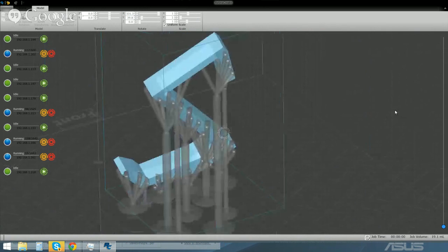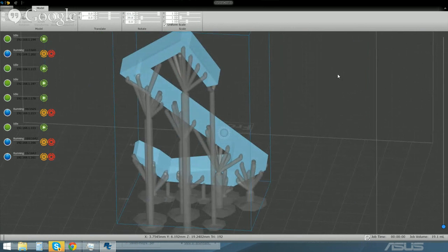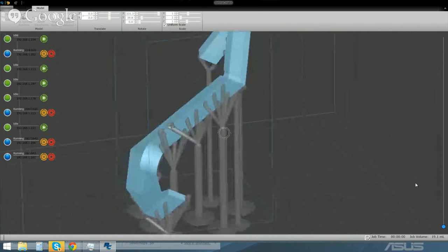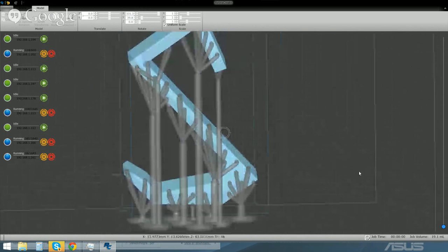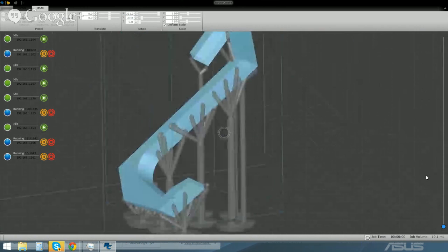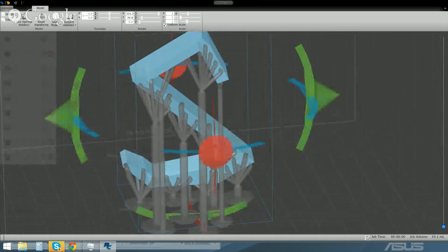But you can see that these trees save a lot of material. This column is thicker, but it's not 9 times thicker, or however many. It looks like there are 7 supports. So this is not 7 times as thick, but it's one base holding up 7 supports. So it saves a decent amount of material using tree supports. So that's something that you'll have access to next software release, as well as some other support advancements.